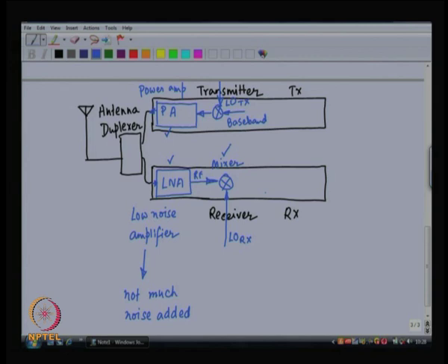So, as I was saying, the transmit side local oscillator will be oscillating at a frequency different from the receive side local oscillator. Why? Why does it have to be the case? Why can't I transmit and receive at the same frequency? Because if I do not have them different, then mostly what I am going to be hearing on the receive is an echo of what I transmitted.